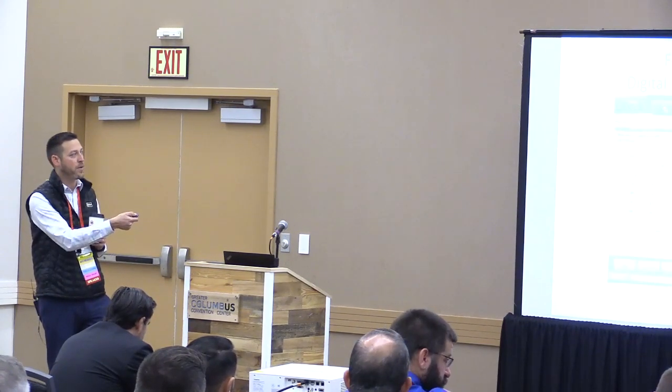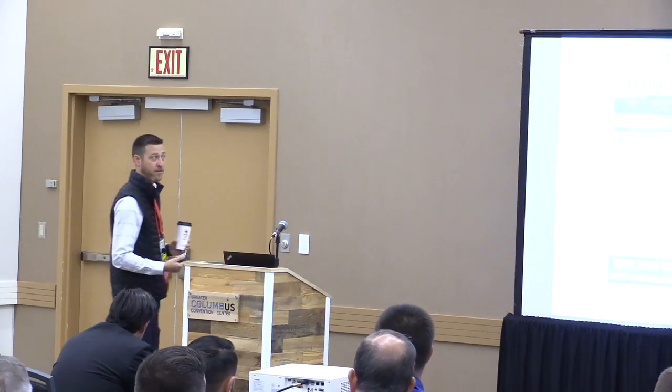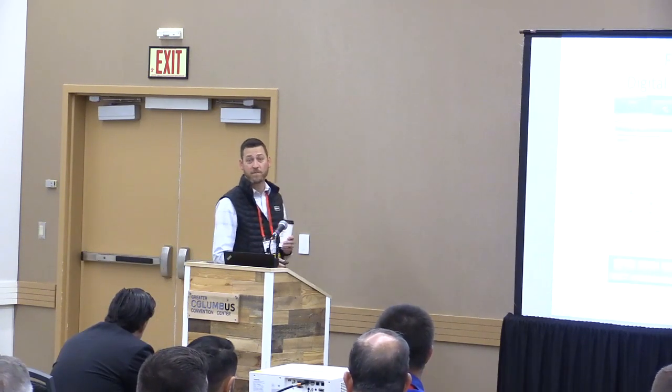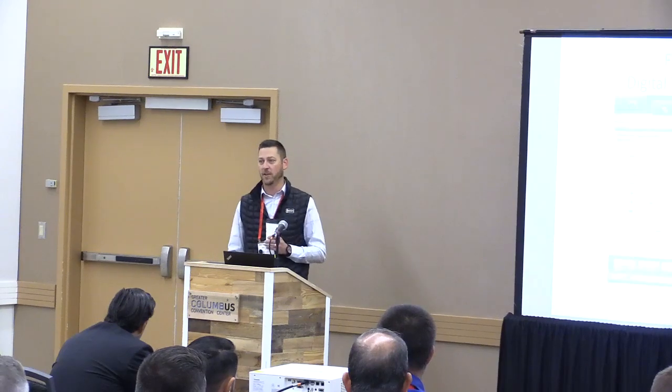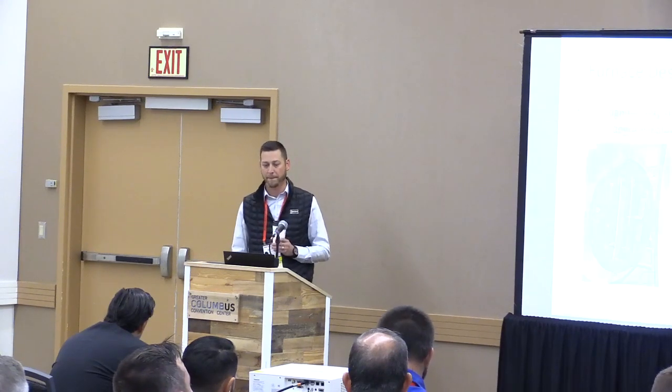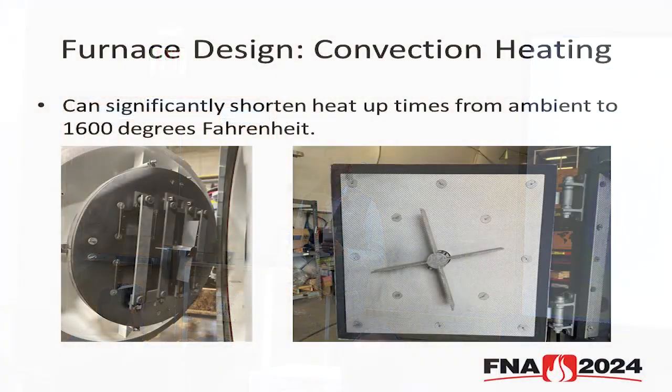But if you're running any parts with any kind of mass to them, you should really have those all at 100%. So when you're advancing from one step to the next, you can have maximum power output in all of your zones. If you don't do that, you're again limiting yourself on the amount of power potential you have in your furnace, and you don't want to do that. Because we generally don't care about uniformity during ramp, we only care about it during soak. Again, there's a few caveats to that if you have light, thin parts that are going to come into temperature really quickly.